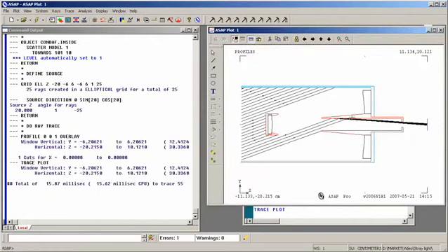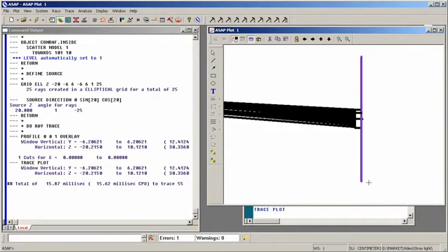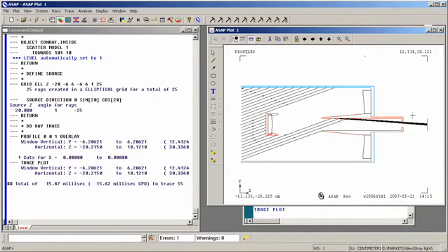Now we see a very different story. Before we had 10,000 scattered rays, none of which made it to the detector. Now we have 30 scattered rays, 10 from each of the incident rays that we see on the inner conical baffle, all of them making it to the detector. So our ray trace is much, much more efficient. ASAP is handling all of the numerical values so that we get the right number.